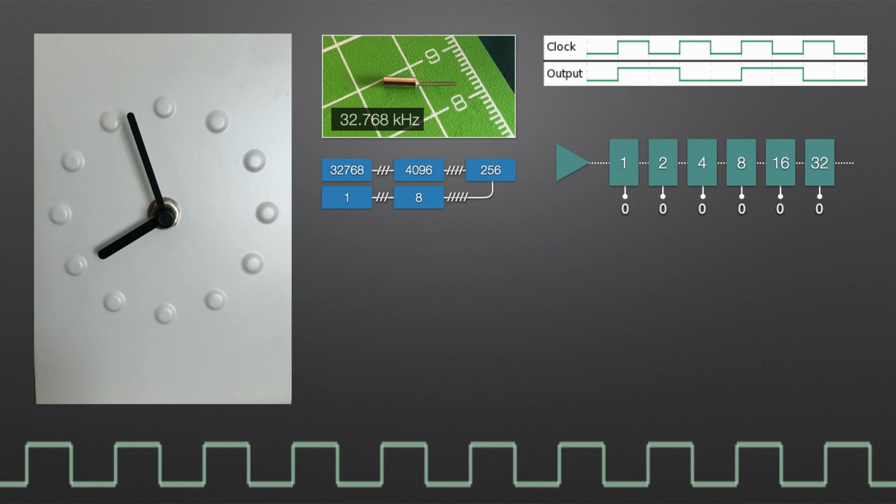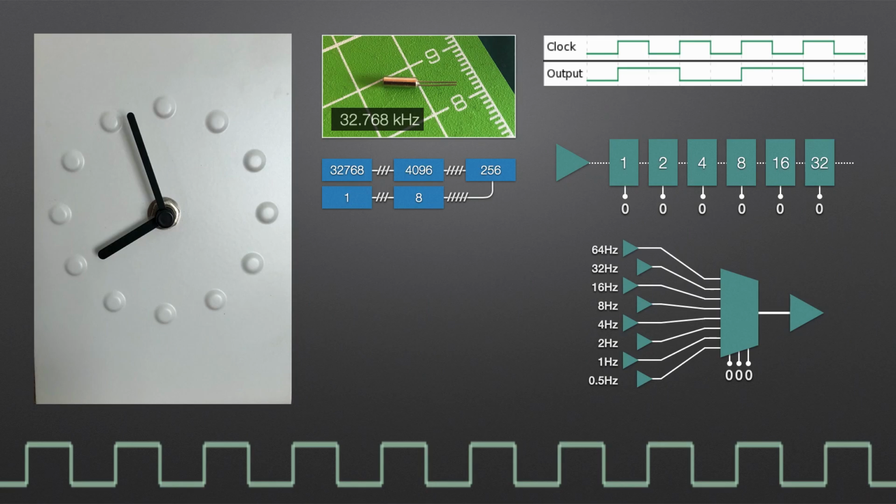Given these ripple counters expose all the intermediate frequencies, we can also take an 8-channel selector chip, so we can pick one of 8 inputs given a 3-bit selector value. This is a nice tidy solution and gives me a range of speeds, all with excellent accuracy. Not that my computer particularly needs it, but there we go.